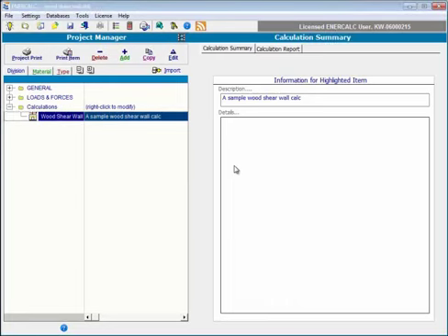Hi, and welcome to this informative video on the Wood Shear Wall module in Structural Engineering Library. The purpose of the Wood Shear Wall module is to evaluate the unit shear in sheathing of a lumber framed wall, to evaluate the chord stresses, tension and compression stresses at the jambs and chords of the wall, and if desired, to design a continuous footing underneath a wood-framed shear wall.